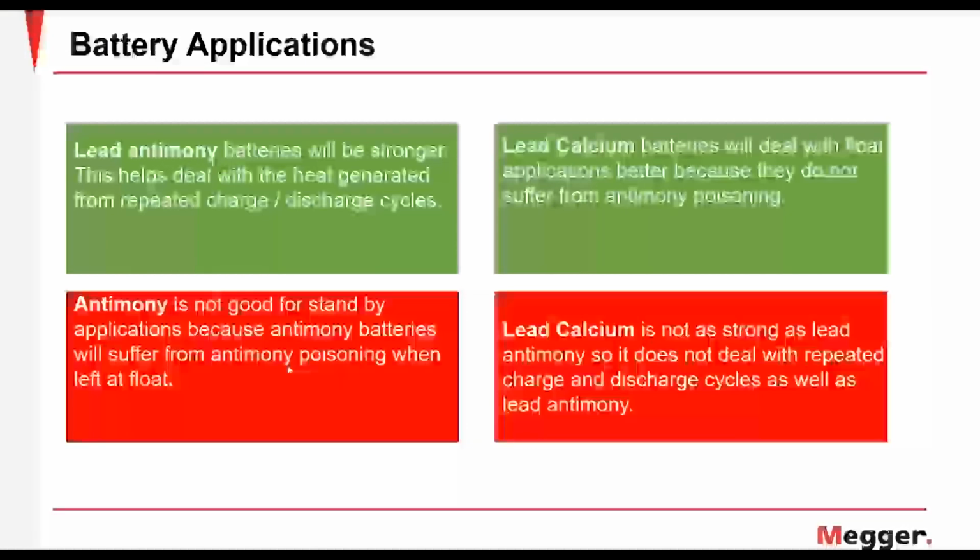in standby application. On the other hand, the lead calcium batteries deal very well with a float application, meaning a standby application, and do not deal very well with repeated charge and discharge cycles. So they are much better in standby application.